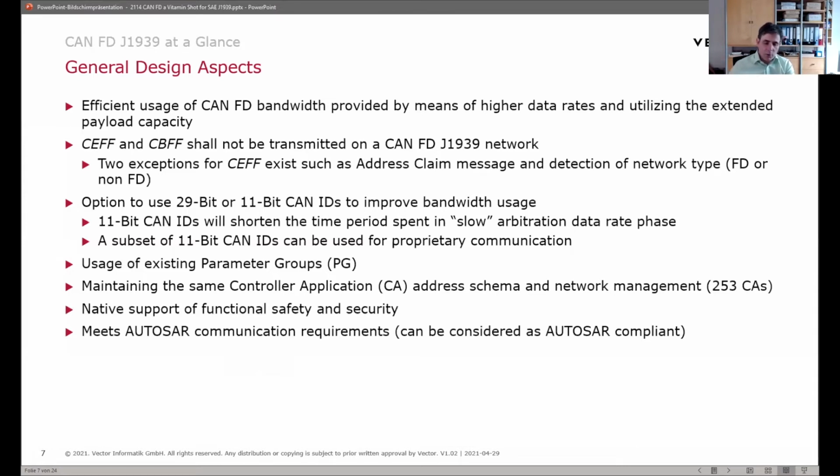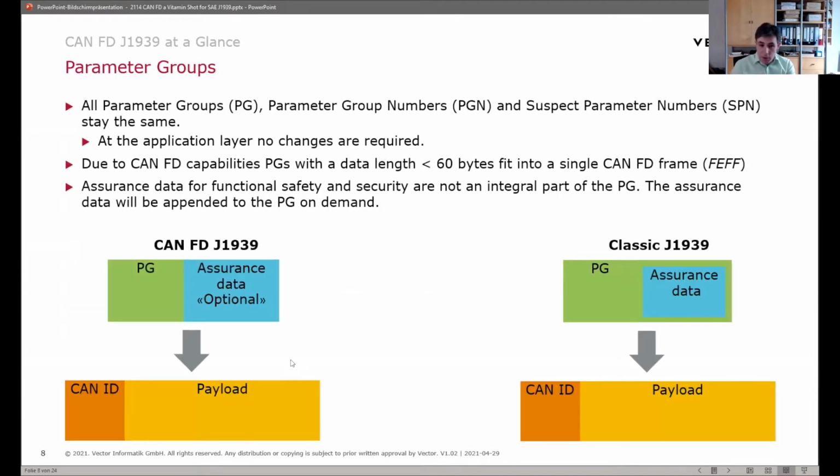Of course, the transport protocols have to be implemented in a special way in AUTOSAR, no doubt about this, but 90% of the communication can be done within the AUTOSAR stack without any adaptation to J1939, which is really great and allows manufacturers to integrate J1939 data links into their proprietary vehicle network environment very easily, very seamlessly. So this is really a major step ahead to have a broad base for J1939 applications.